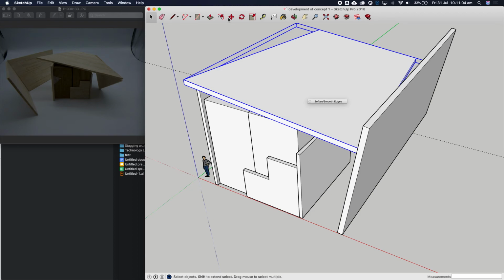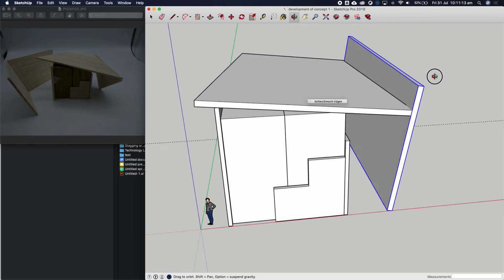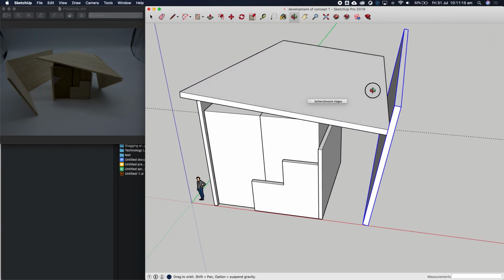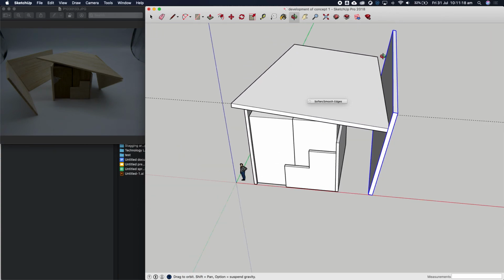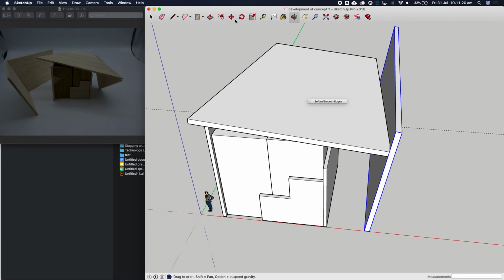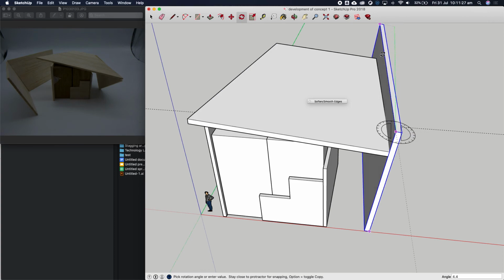Okay, I'm going to go over here, move this object. I need to select the object first. Select that object. Let's move it around so I can actually see what's going on. This is kind of there. I need to use the rotate tool, click on this, making sure that it is on that black angle, because it's an arbitrary angle. Bring this around so it locks up against there. You can actually see this combining, so you can see that the black line's disappearing. Yep, so that's done there. Sweet, we're looking pretty good now.